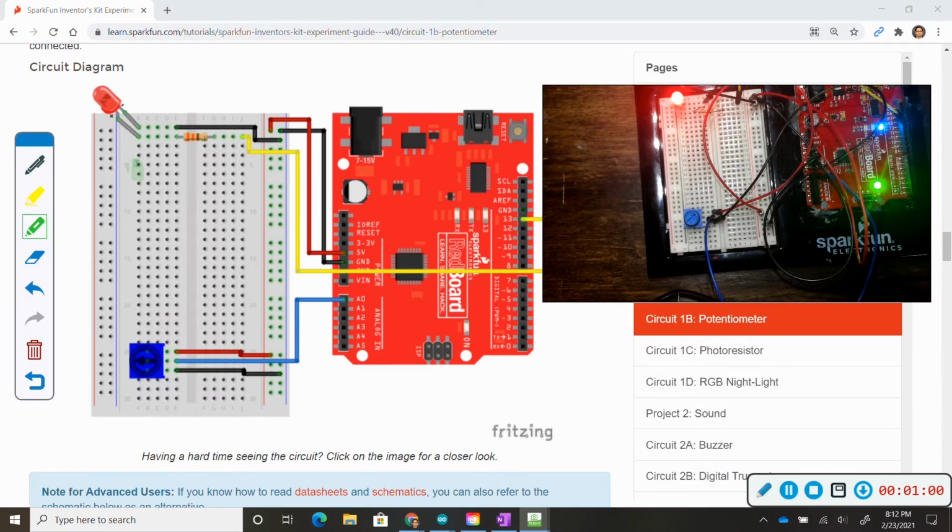I'm going to add my new LED to this location here, column A, rows 5 and 6. And then I'll connect the resistor here, just like this 330 ohm resistor. I'll have another black jumper wire going to my ground. It's going to go from here to there. And then finally, I'm going to add another wire on pin number 12, because remember, I need to send electricity